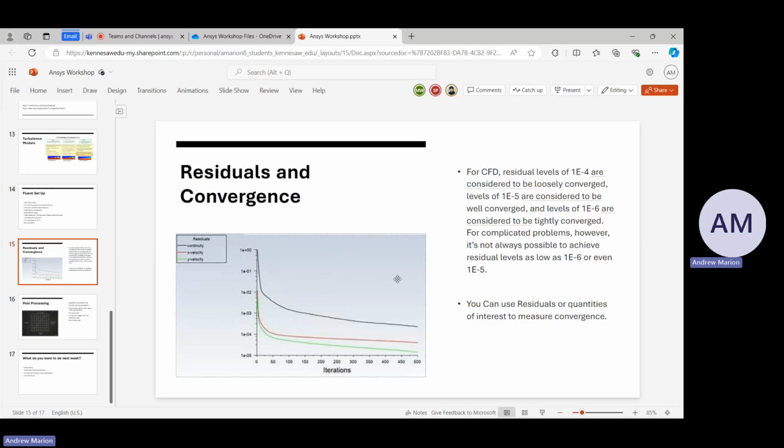Often you'll have to start and stop your simulation to see how the graphs are going. If your graphs are getting really wide bounces, you'll probably want to tighten your relaxation factors so that the bounces can constrict. If your residuals aren't moving much at all and it's just staying at the same number, but it's not going down to convergence, it's just being stubborn, you might want to widen your relaxation to make it bounce a bit more and try out lower values.